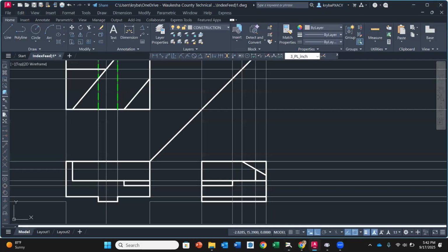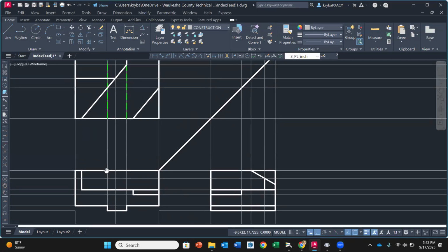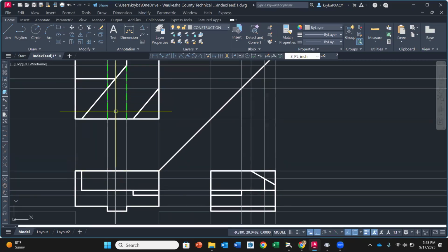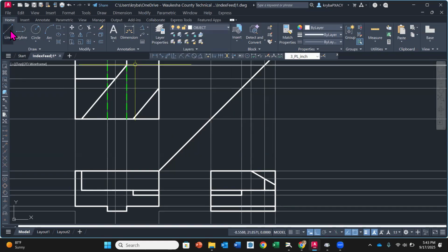So let's go back to AutoCAD. So this is going to remain. And then when it crosses that angled portion, that's where I'm going to go back to my object line layer, line right there. I'm going to start my line, and I need to get my ortho off. It's going to go back to here and down. That's it.